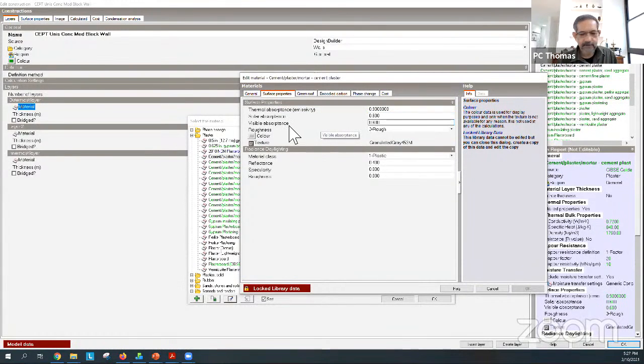And there is a visible absorptance. Now, if you remember, your basic equation is that transmittance plus reflectance plus, what's the other one? Transmittance, reflectance and absorptance is equal to 1 at any wavelength, right? So in terms of an opaque material, you don't have any transmission. You've only got reflectance and absorptance, so if you have the absorptance, the 1 minus of that is the reflectance. So you can adjust that there.